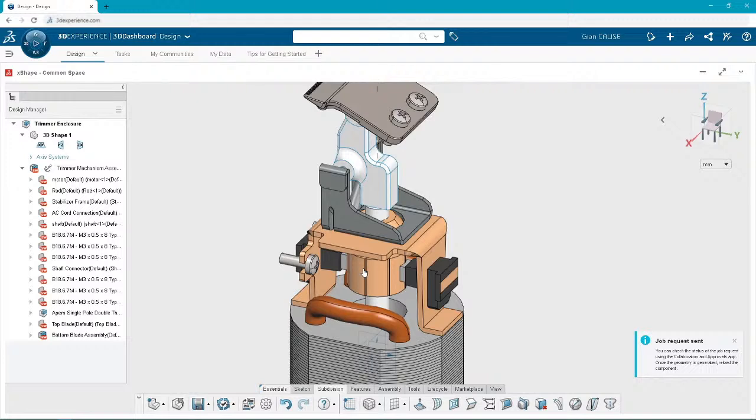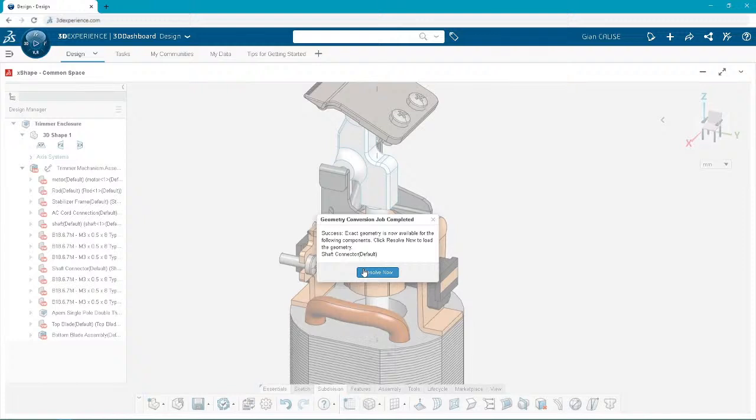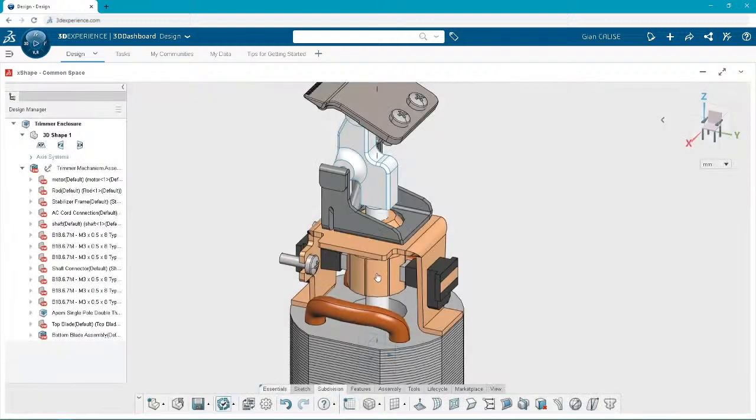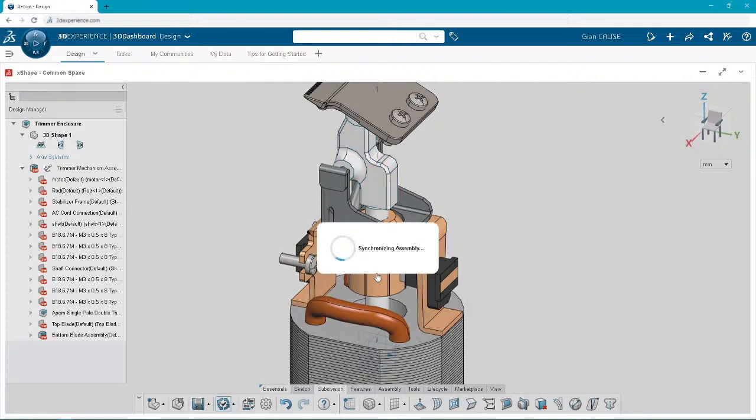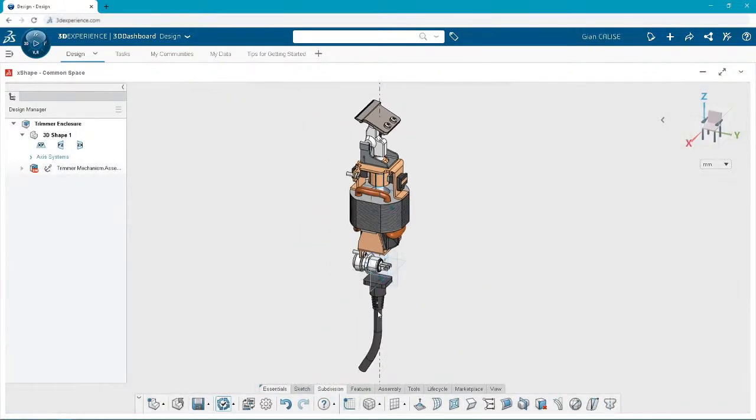That's why we threw this in, because it's another new enhancement to the user interface that now lets you know when it's done, and even gives you a button to resolve the geometry. You'll see your model turn to black edges. We can start using those edges in our sketches and features. So now that we've gotten that out of the way, maybe I want to hide that axis quick, and then let's get into the subdivision stuff. Let's get into the cool part of this modeling.